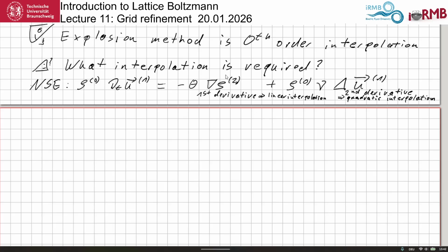And what you see, so it's funny, if you have linear interpolation of the velocity, you will see a kink or a jump in the pressure, because the pressure will try to balance this. So velocity usually looks good even if it's wrong, but pressure then will be wrong. Pressure and stress.